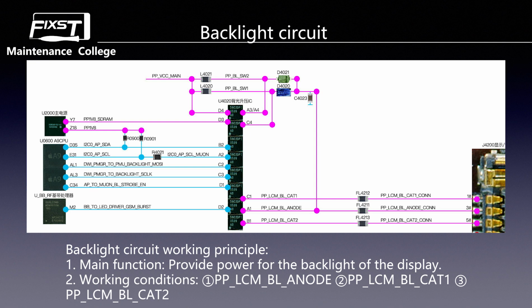It is not very clean, but we can see that. And if you can see the logo, it's okay, but not very clean. It means that the display circuit has no problem, and the problem is in the backlight circuit. And it is the same.